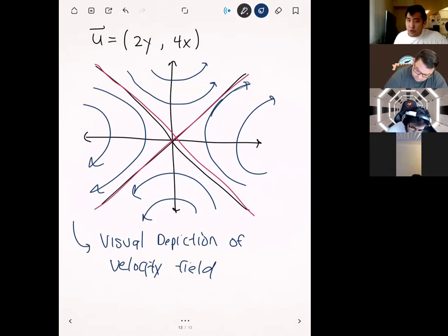Remember, the big difference now with differential fluid analysis is that we're more interested in what the flow patterns look like and what the pressure patterns look like. We're interested in seeing the details of how the flow actually looks in our domain. That's very different from our control volume analysis, where we looked at a control volume as a whole, and just looked at the overall variables like pressure, energy and momentum. Now we're getting into the details of what the actual flow patterns look like, and differential fluid analysis with the stream functions gives us a way to actually do that.